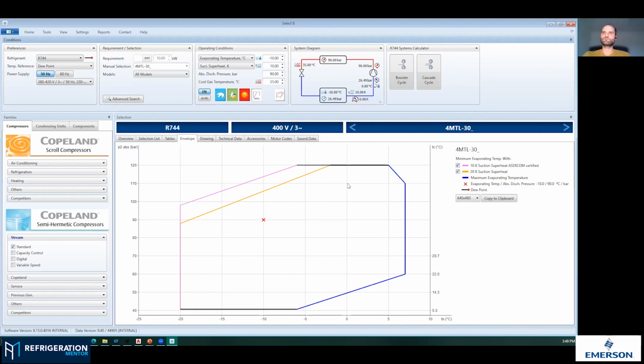Because when you design the motor for a given displacement, pressure, and temperature operating map, you typically have the highest motor efficiency somewhere close to the high load or a little bit left from the high load. But if you go to the left, the compressor is taking less power from that motor. The efficiency of the motor goes down, and that's why the motor as such is generating more heat. In combination with lower refrigerant mass flow along the motor, it is heating up more and more. So this area is really the most critical for motor overheating typically.